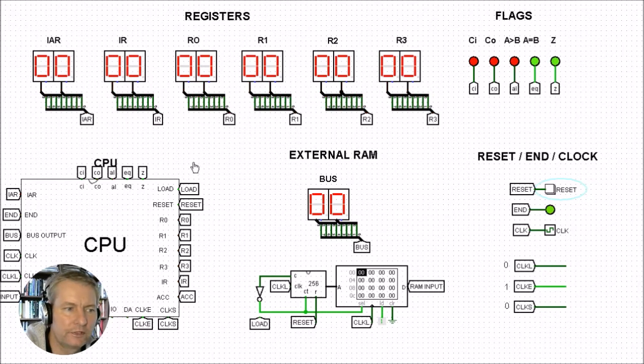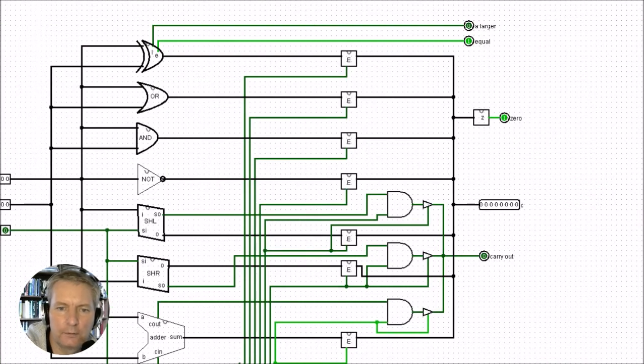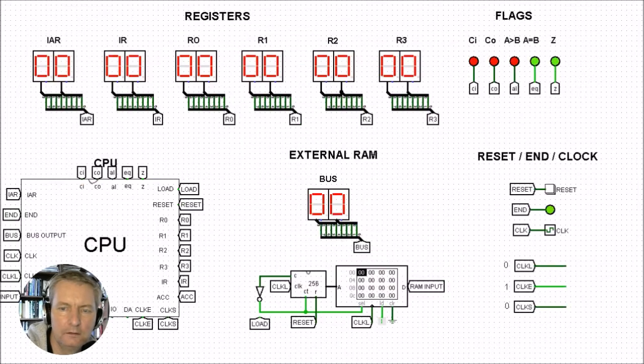you'll see it's reset all of the registers to 0. And you note here the flags as well. You've got these set at 0, we've got A equals B, and we've got 0. You can see the A equals B if you drop inside. It's going to be A equals B because initially it's starting off with 0 at the ALU, so whenever it adds up it gets a value of 0, so this 0 flag is going to be set.